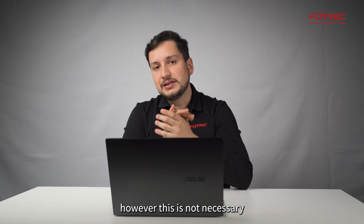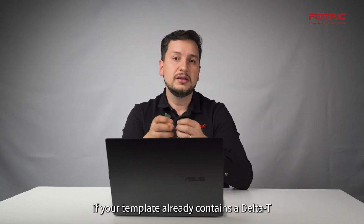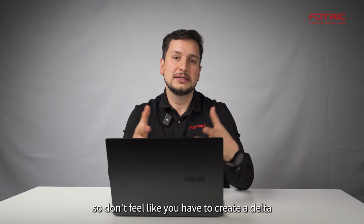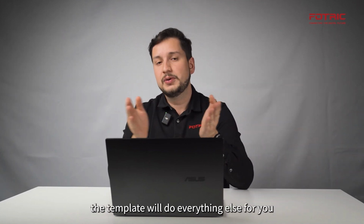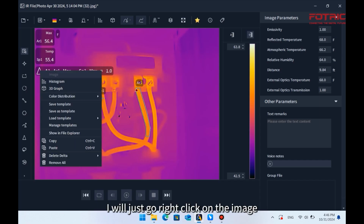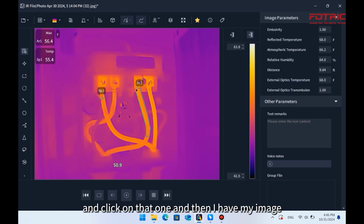However, this is not necessary if your template already contains a delta T. This is just for analysis purposes. So don't feel like you have to create a delta for every single picture that you have. If you have one spot and one area, that's enough. The template will do everything else for you. So if I don't want the delta, I will just right click on the image, delete delta, and click on that one, and then I have my image just fine.